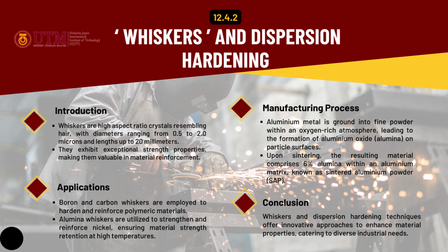12.4.2 This subtopic is discussed about whiskers and dispersion hardening. Introduction: Whiskers are high aspect ratio crystals resembling hair with diameters ranging from 0.5 to 2 microns and lengths up to 20 millimeters. They exhibit exceptional strength properties, making them valuable in material reinforcement.